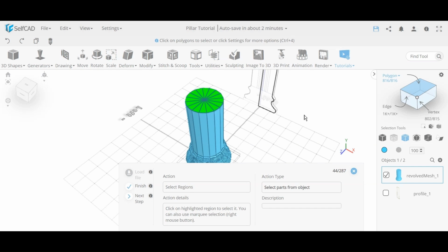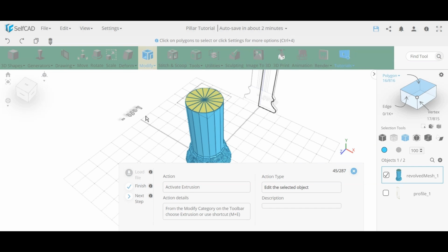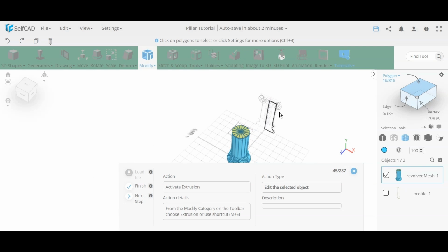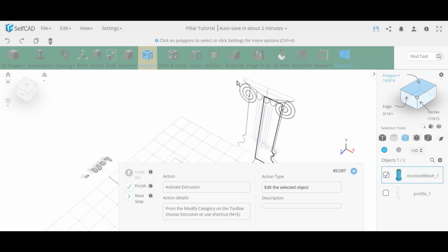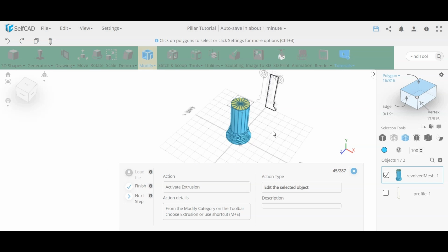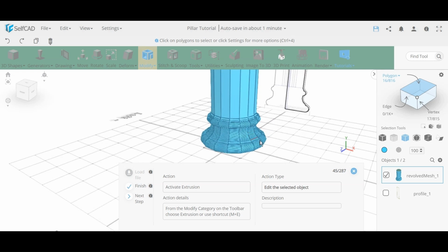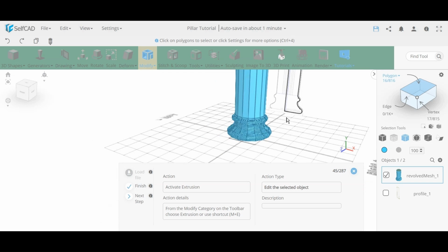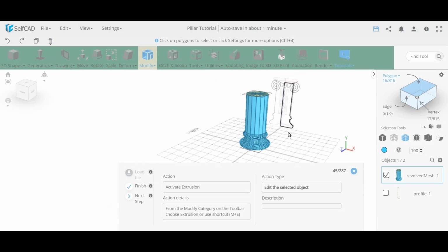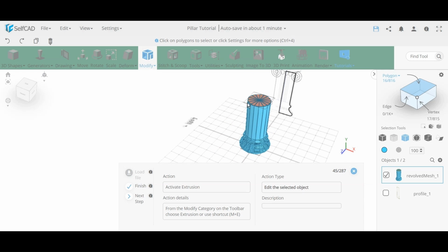So we're going to activate polygon mode, and we select this polygon, and if you see the shape over here, this has a top that is kind of not rounded. So revolve is limited to things that are kind of rounded. I mean, you can make fewer edges. If you make 4 edges, then it would be kind of squared, but then the entire shape would be like that. So in this case, we have a unique situation where we have the entire thing rounded with the exception of a top and bottom. So this is why this is going to be done in a different way.